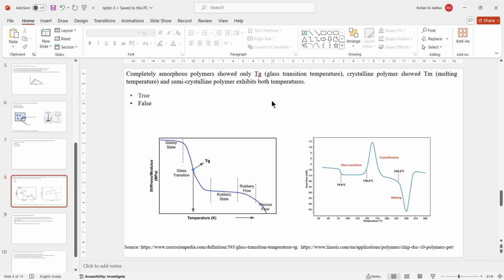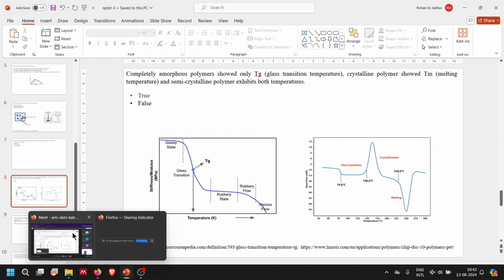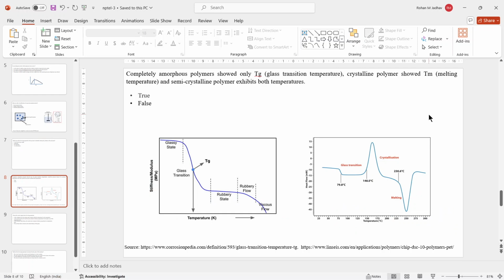That it will reach a threshold temperature where the chains suddenly have enough energy to move around, and because of that, your polymer will start moving around. Basically, it's molten. And that's the exact reason why crystalline polymers will show a good melting temperature and amorphous polymers show a small glass transition temperature also.